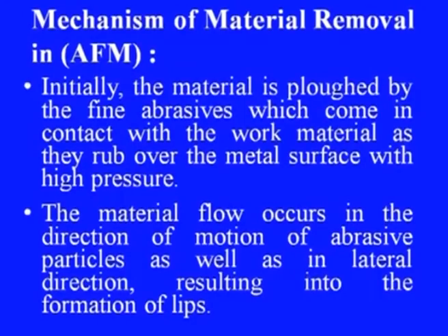The material is initially fluffed by fine abrasives which come in contact with the work material as they rub over the metal surface with high pressure. The material flow occurs in the direction of motion of abrasive particles as well as in lateral direction. This results in the formation of lips.